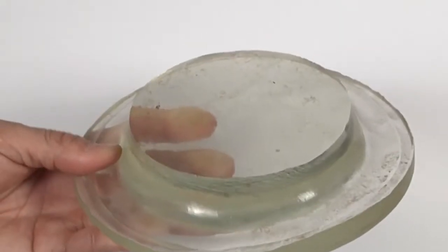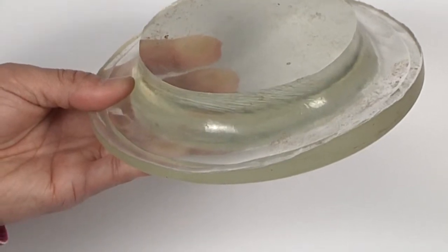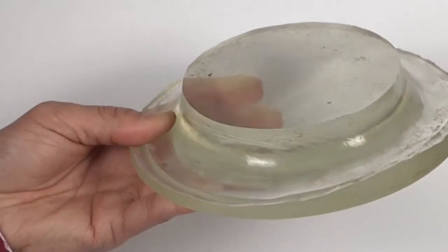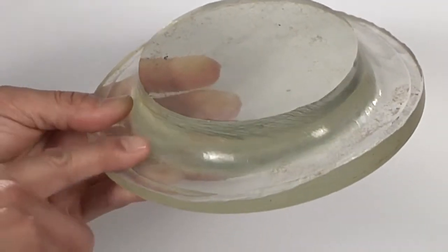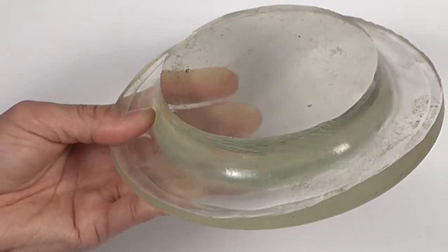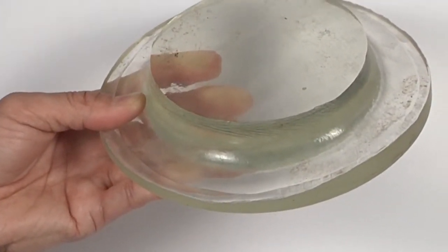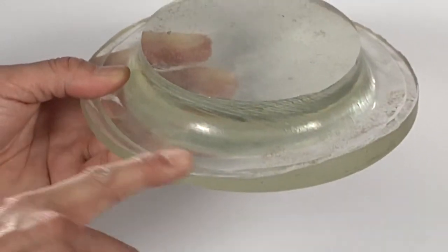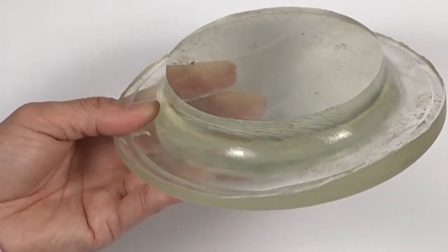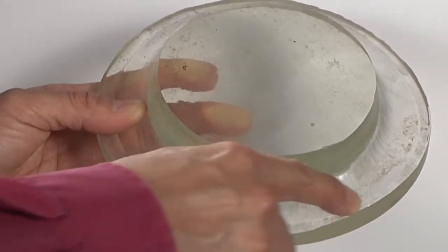Okay. Looking at this again, I can point out where the seals were. This was sealed along the side walls. You can still tell that the side wall was vertical right around here, and this is where the seal was, right along here. You can also tell how the water ate away at the glass. Here at the center, where the stress is the lowest, only a small amount of glass was lost. Here, at the seat of the seals, a whole lot more glass was lost, and in fact, the loss of glass was severe enough to leave an easily identifiable ridge right along here.